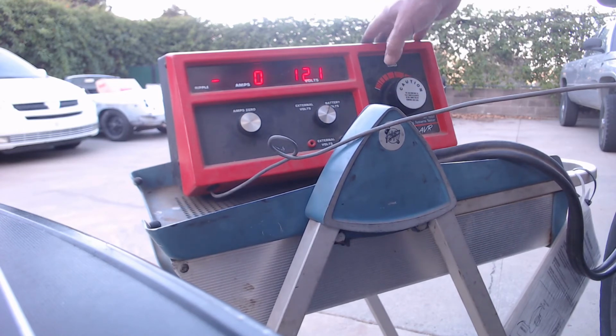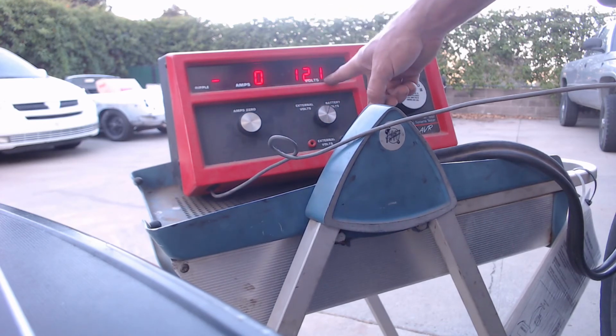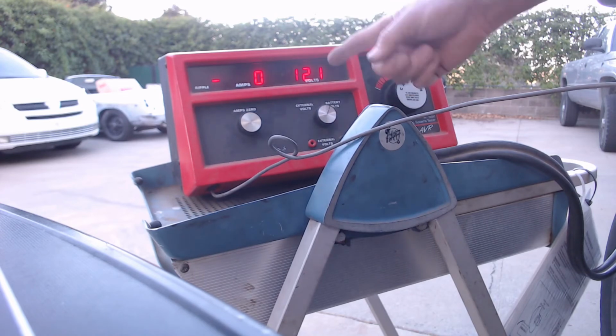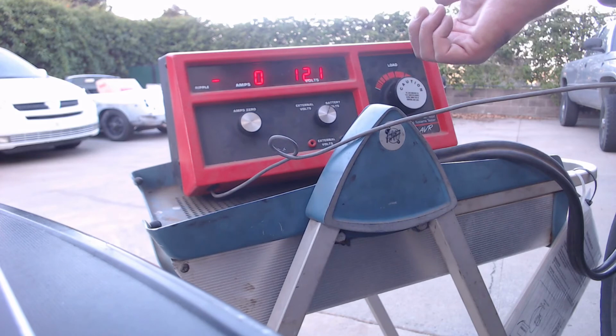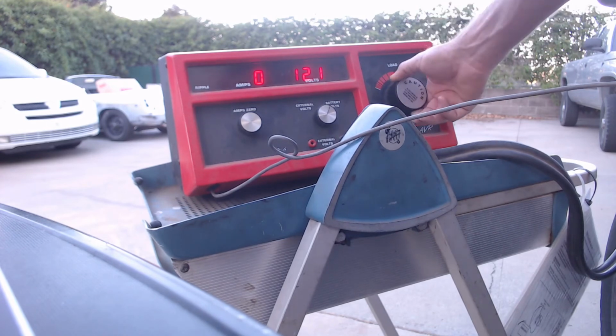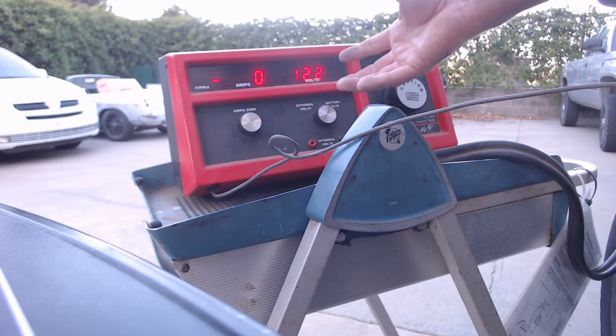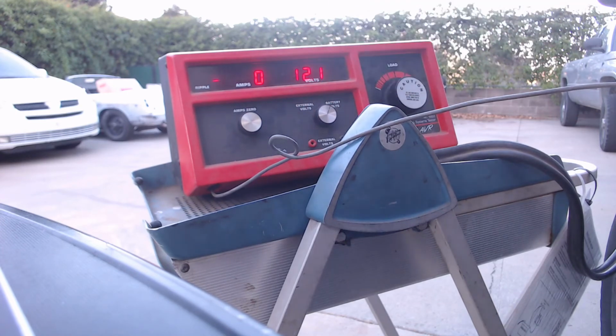A lot of modern cars won't let this test work. I believe this '07 will. It's old enough. We're going to read the max amperage and not let the voltage drop below 12.6 volts at 2000 RPM. So once again, I put the pedal depressor on the throttle, hold it up at about 2000 RPM. I'm going to come out here, load this, get the max amperage at 12.6 volts. We are stressing the alternator. So let me get that set up.